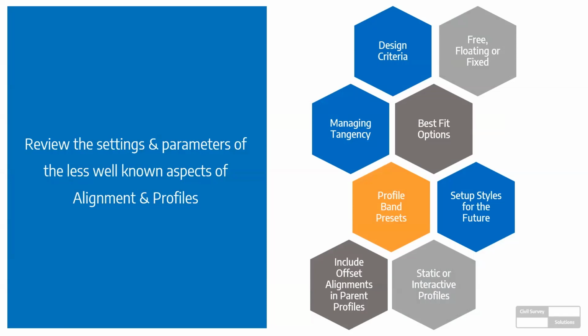There's a lot of functionality in the Civil 3D long sections or the profile views, which means there's a lot of controls that you have to navigate. So the flip side of having absolute control is having to set up a lot of settings and a lot of styles. But once that's done, you can save those styles away, and you're good to go.